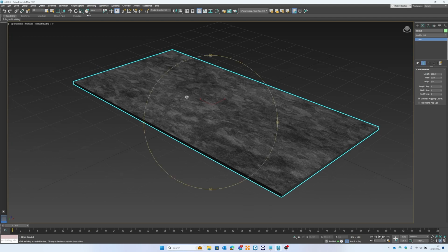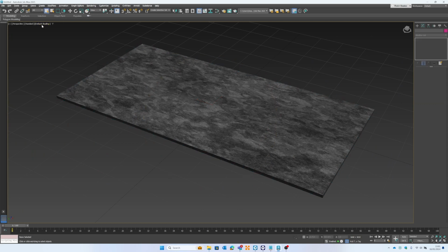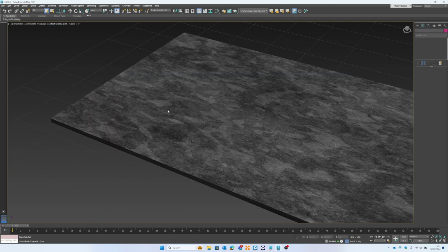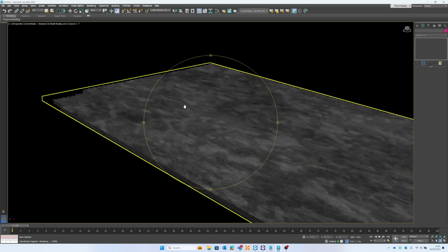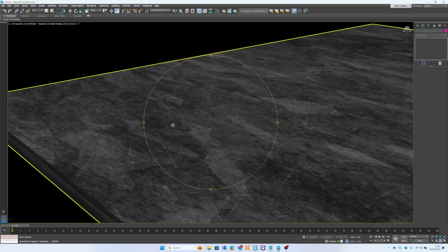particular component. And if you want to start to get a quick handle on this, either I can do a quick production render, or I can actually start turning on things like active shade inside of Max. So if I use my standard viewport style here and use active shade, this will turn on the renderer inside of my viewport. So it will make your viewport a little bit slower. But with that, what you'll get is a rendered looking viewport, and you can start to get an idea without having to come up and down and hit render, render, render of what the material is going to look like, what the lighting is going to look like. And then you can go and have a play and have a look and tweak and adjust.